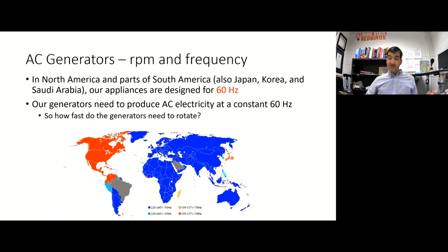What you have to do is have a converter, and that converter station takes in one frequency, converts it, actually rectifies it to DC electricity, and then inverts it again to some other frequency of AC electricity. So as you can imagine, those converter stations are pretty expensive and they have a limited capacity. So Japan does have a limited capacity to take electricity from the north side and convert it into a different frequency and power the south side and vice versa, but it's very limited.